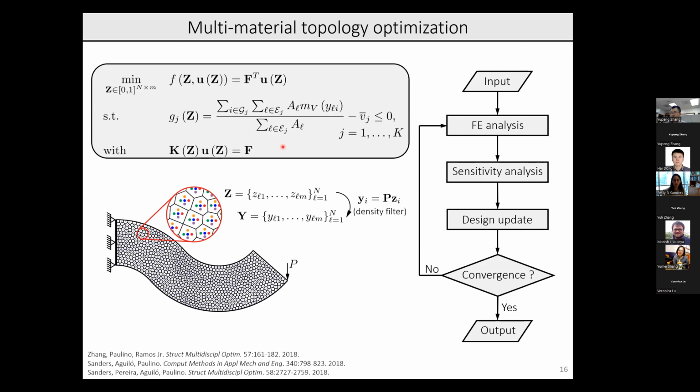So let's regroup a little bit. We saw our formulation. We saw how we can use interpolation functions to both penalize undesirable features in the solution and also to translate our design variables into stiffness properties that allow us to essentially solve for our displacement field. So right now we're here in our algorithm, okay? So we need to compute derivatives and then use those derivatives to update our design.